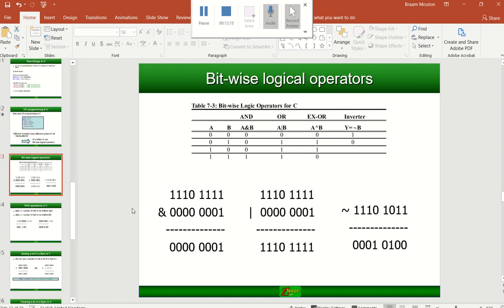We will see here that if I use AND, and this is my input A and B, if I AND 0 and 0, it's going to be zeros. Whenever you see a 0, there's a 0. Only when it's 1 and 1, you'll see a 1. If you OR, if there's a 1 on A or B, like there's a 1 on B, the output will be a 1. A 1 on A, output will be a 1. 1 or 1, it will be a 1. And only when it's 0 and 0, you'll get a 0 if you OR them.